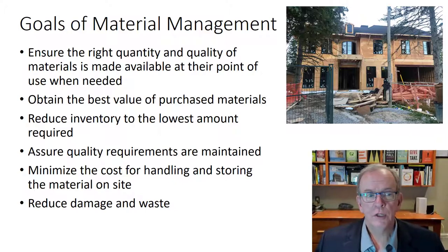Reduce inventory to the lowest amount required. We definitely don't want to have more on a site than we need to, right? So this doesn't look like a very good site. Lots of waste there, stuff just piled up. It's going to be warping, twisting, cupping, checking, and generally just in the way of us functioning on the project, not to mention that it's a safety hazard, etc. So reduce inventory to the lowest amount required.